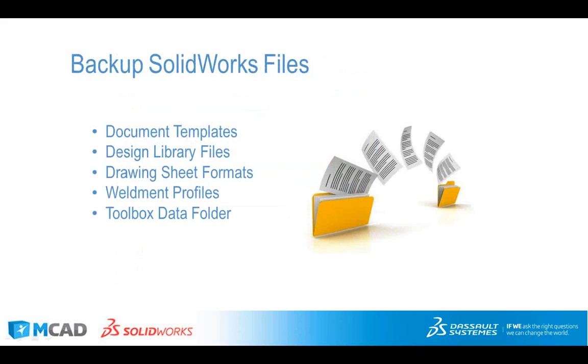Okay, SolidWorks files. Anything in the SolidWorks installation directories is going to be removed when we do this clean, when we do the uninstall. So if this data is located in other locations, you should be okay. If it's on the network, well, we're not going on the server to delete some folders. We are just removing it from our local system. But if you do save things into your installation directories, your templates, design library, sheet formats, weldment profiles, or even your toolbox data, those are things that you'd want to back up.